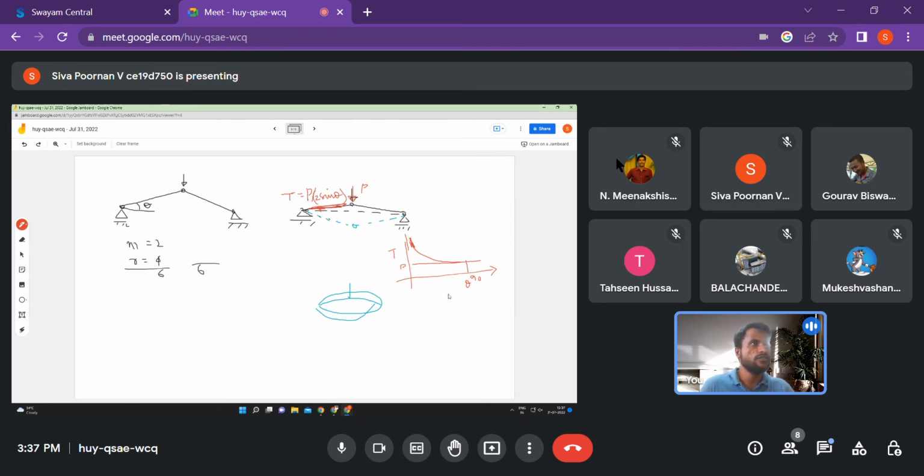Okay. So that is an example where we need to be careful. Our Maxwell's rule will say that it is statically determinate, and that means that it is stable, but actually it is not. So we need to be careful. Maxwell's rule is just an indication. It is not a rule per se, just an indication.